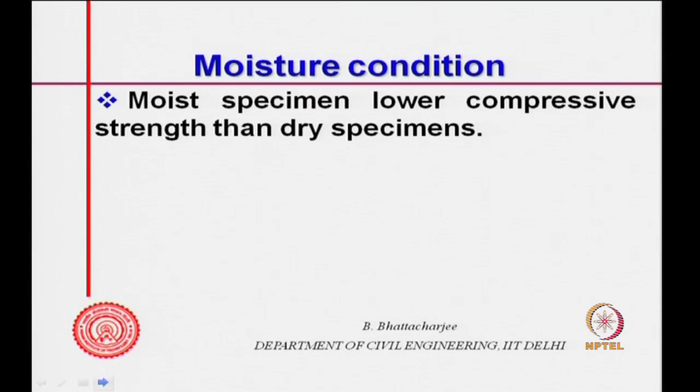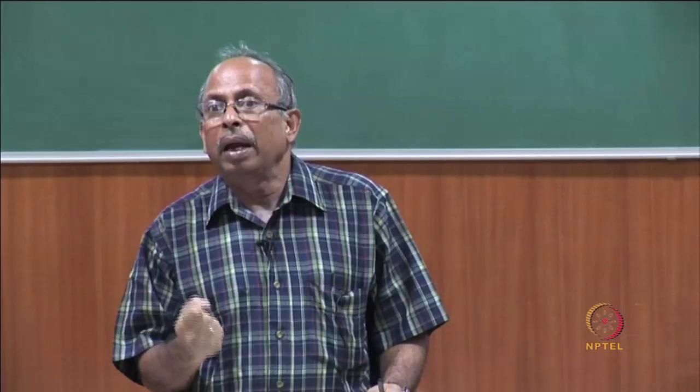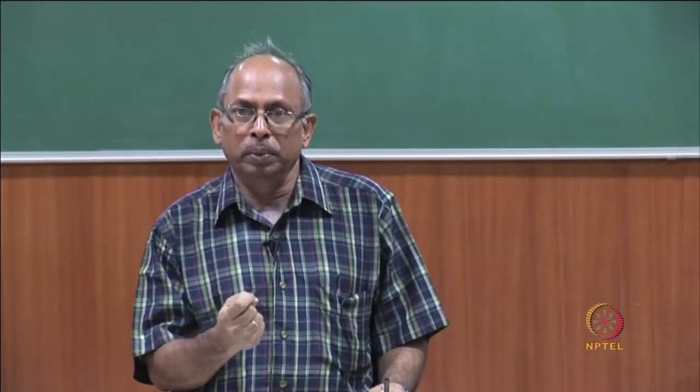Moisture condition: a moist specimen shows lower compressive strength than a dry specimen. I just mentioned it the other day, because of adsorbed water. Now, what is adsorbed water? Water vapor can be adsorbed, and that actually forms a layer.